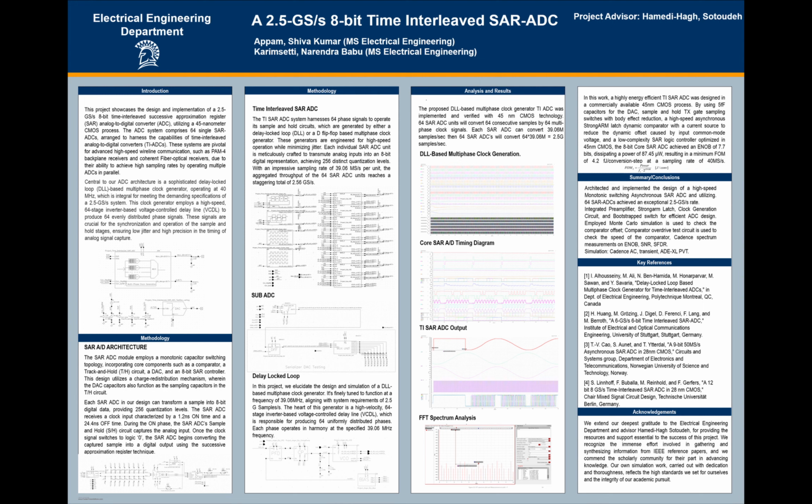This is our sub ADC structure, and this is our DLL structure. In the DLL we have a PFD circuit, a charge pump, the voltage controlled delay line and bias circuits. Even the power supply we generate using a bandgap, LDOs and bias circuits. For the entire requirement of the time interleaved SAR ADC, the clock generator circuits, power supply units, core ADCs and the time interleaved structure, everything is on the same chip.